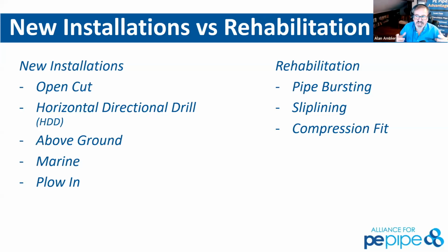If that's not ample enough, you can also stage dewatering around that trench down to 16 feet, and then that will remove the water itself. If your excavation is lower than 16 feet, then you'd have to have stage dewatering as we go through that. But thanks. Keep those questions running, guys, and Dan, I'm not going to stop you.